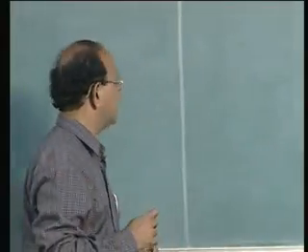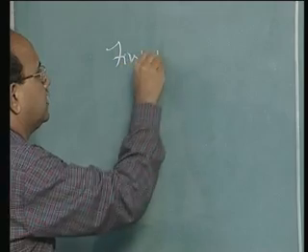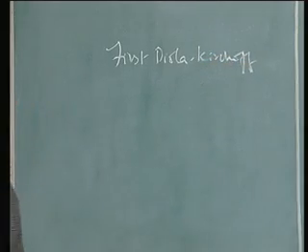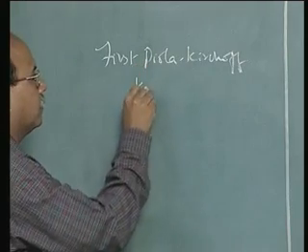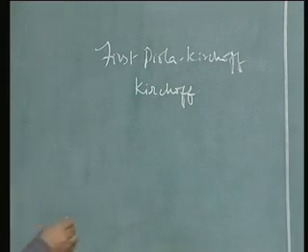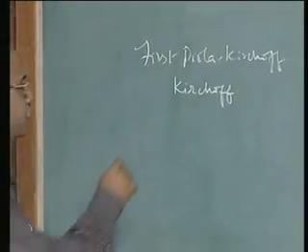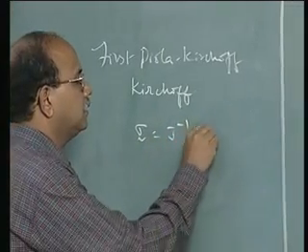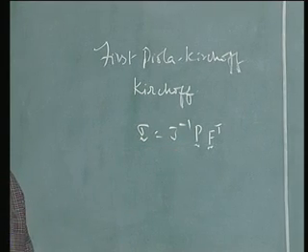In the last class, we had looked at two stress measures. We call the first stress measure the first Piola-Kirchhoff stress measure. Of course, this is apart from the Cauchy stress, which you already know. Remember that we developed a relationship between the Cauchy stress and the first Piola-Kirchhoff stress, which can be written as sigma is equal to J inverse P F transpose, and this P, which we called the first Piola-Kirchhoff stress, right?